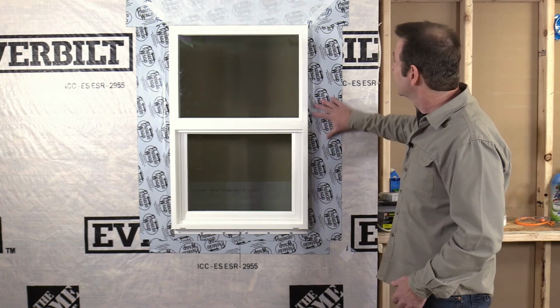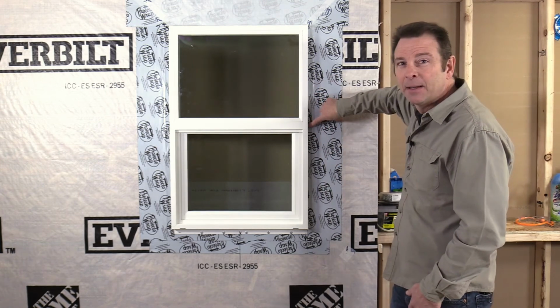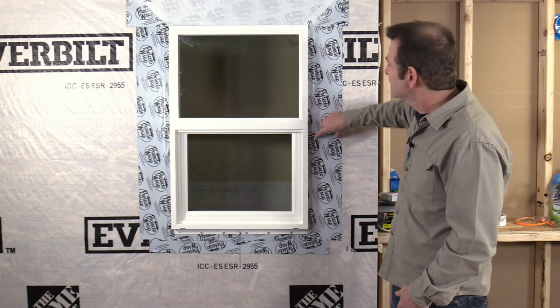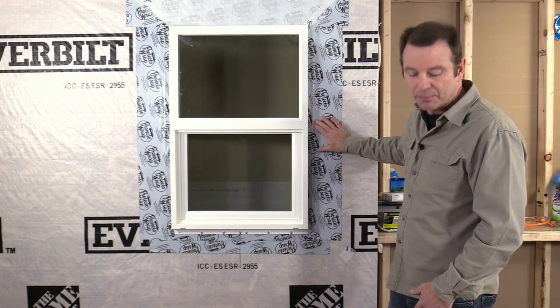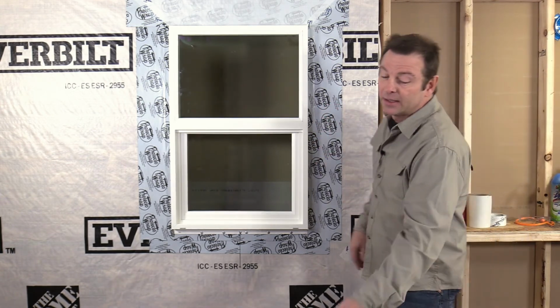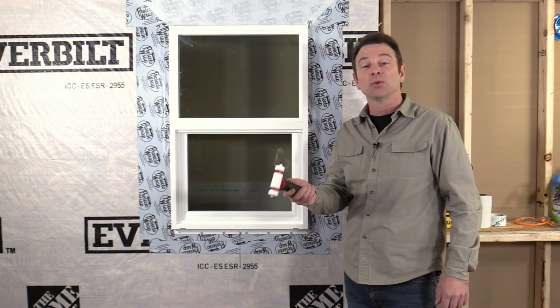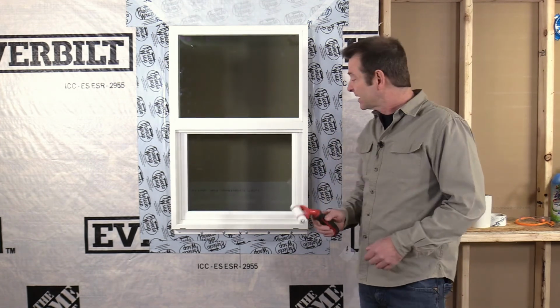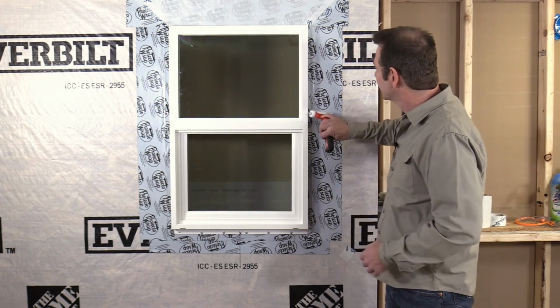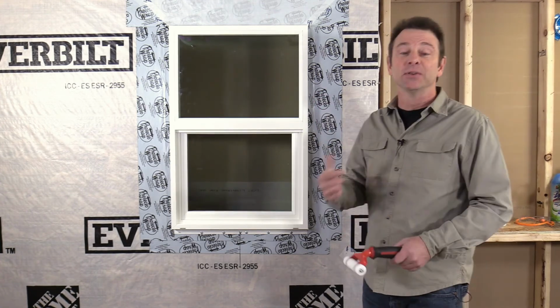So these side flashings, this is a 6-inch piece of bitumen straight flashing. These need to be rolled or pressure applied. They should be using a specific tool that's a roller, and this allows a lot more pressure on these surfaces than you can do by hand.